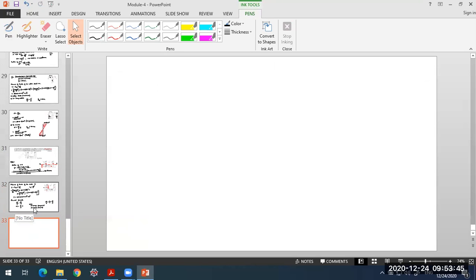Now we'll go for determining the moment of resistance considering both of the permissible stresses here. So first, I consider the moment of resistance by taking the permissible stress in tension. The moment of resistance of the section: first is sigma 30 Newton per mm square tension.